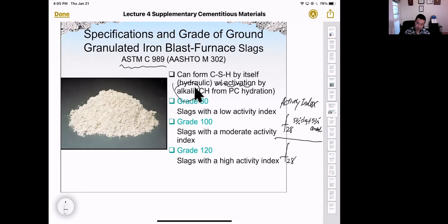So F28 means the compressive strength of the specimen at 28 days. Okay, the specimen of the control, which is 100% cement. Other properties such as water cement ratio will be the same. So we get the ratio of the control and the 50% slag and 50% cement.